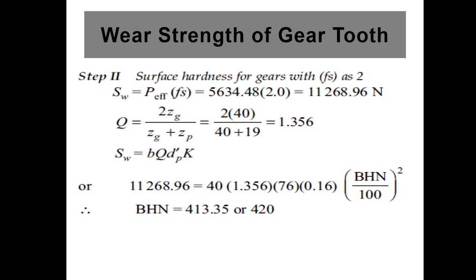We already calculated P effective, 5634.48, and the factor of safety is given as 2. So we multiply by 2 and get the wear strength, which is 11,268.96 Newton.